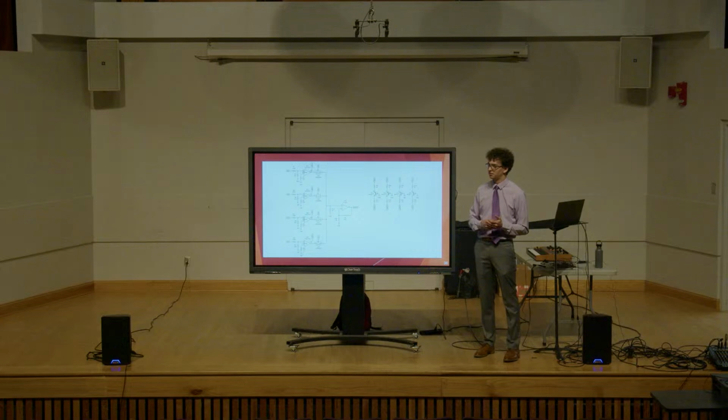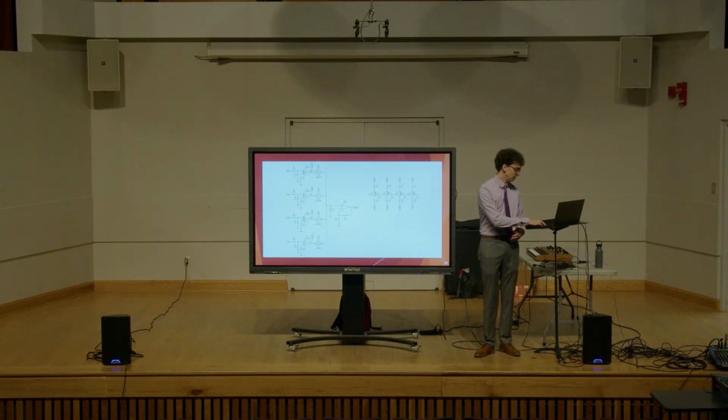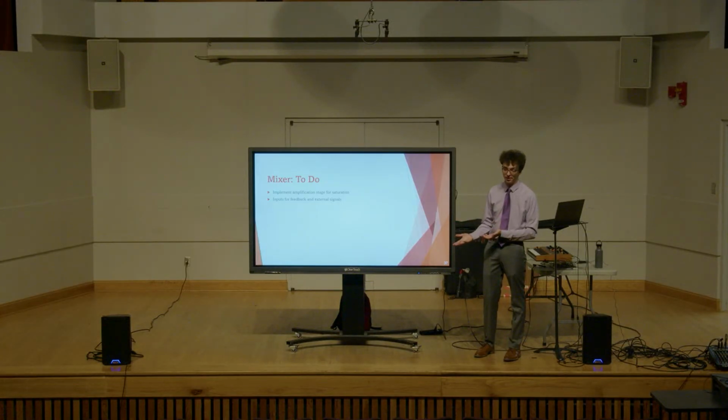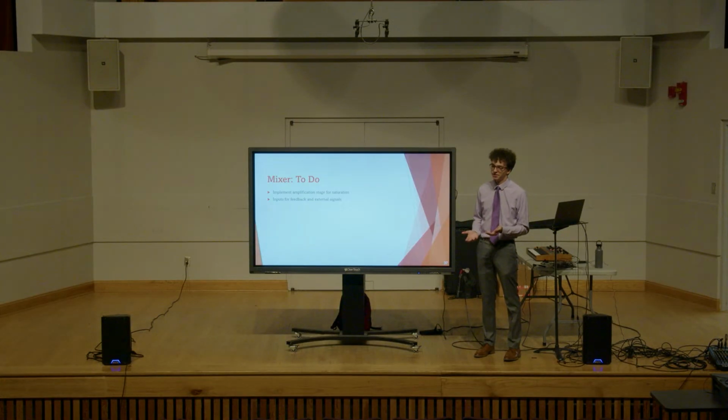But what I have not given a whole ton of thought to yet is how I'm going to implement the amplification stage at the end to start things clipping and to start that sort of drive that I'll want to implement eventually through the circuits, the filter. I also have not implemented the external input, but again, I don't imagine that'll be crazy. Just set an expected value for input voltage levels, and if it surpasses that, just make sure it clips so it doesn't break anything.